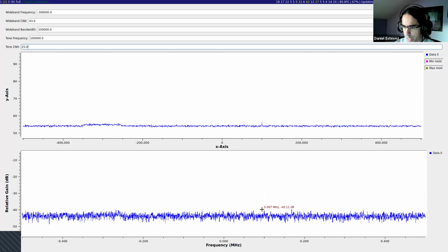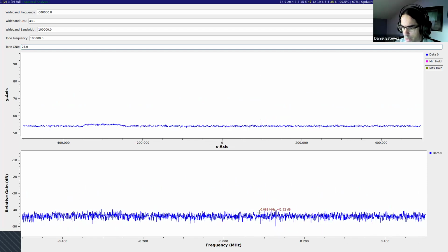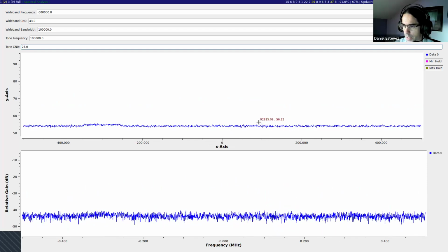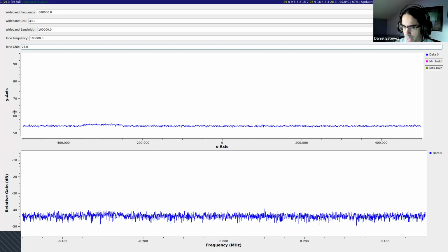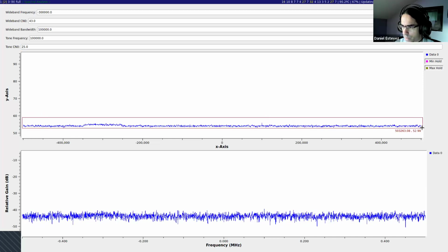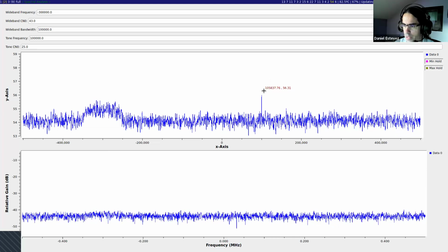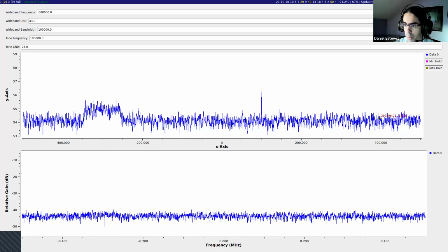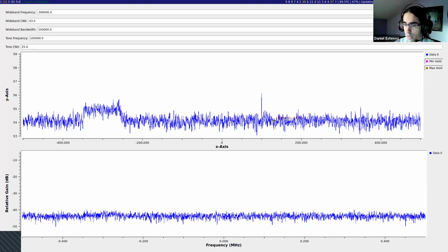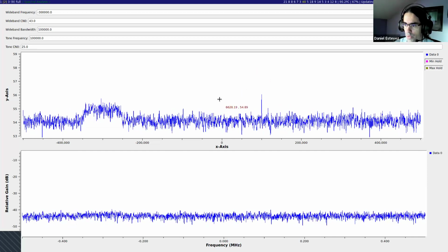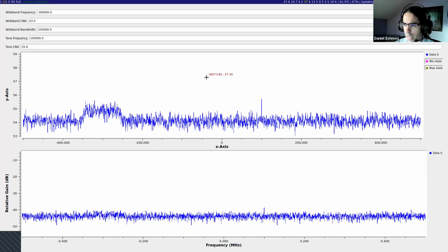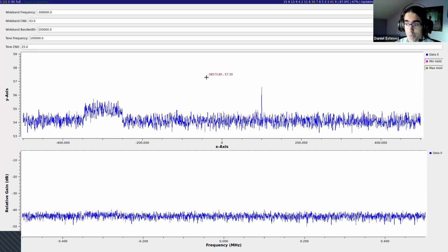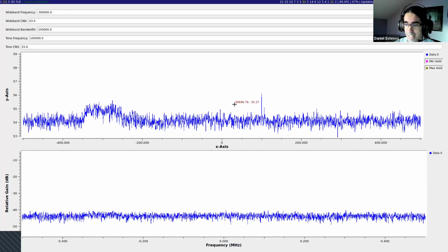It's there. If we know exactly what it is, we can try to see it, but there are other peaks which come up occasionally, which are not the signal. And in here you can see it's a small peak. I can zoom in. It's a small peak, but it's always there because the noise variance has been reduced by properly averaging the data through 1 second. So this is the proper way to construct a good spectrum analyzer, and we can detect Voyager with this technique.